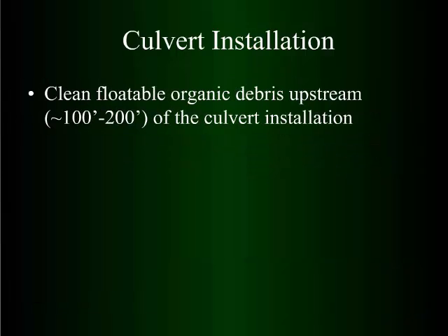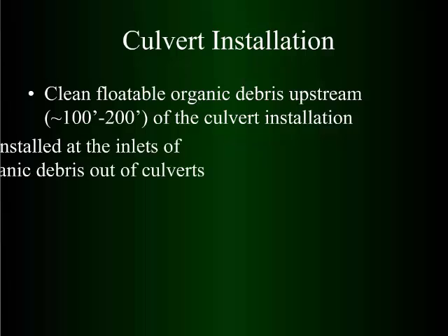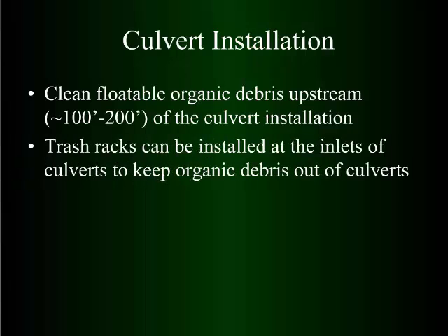Some people may or may not want to do this. I don't know if I have the energy to go up and try to find anything that might float and clean it out so it doesn't plug my pipe. But trash racks, don't see too many of them in Utah. Basically, they look like a cattle guard across the top of the pipe so that big material can't enter the pipe. They work pretty well, but you have to maintain them as they themselves can become a dam. So if you have trash racks, you have to have a regular scheduled service to remove the debris from them.